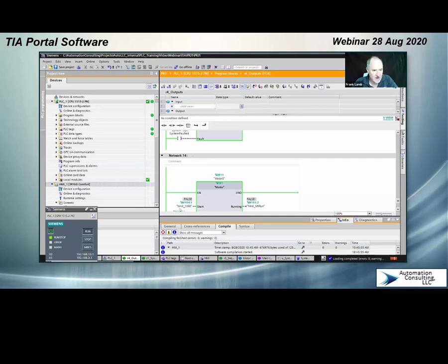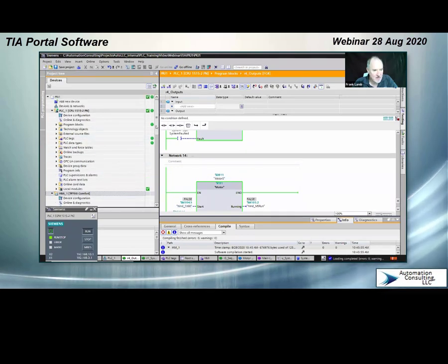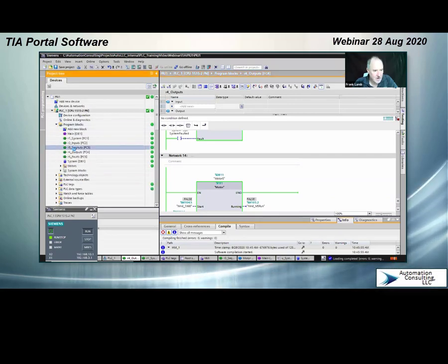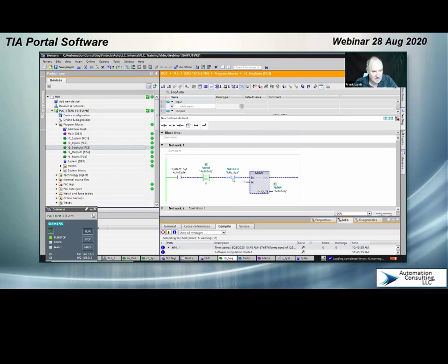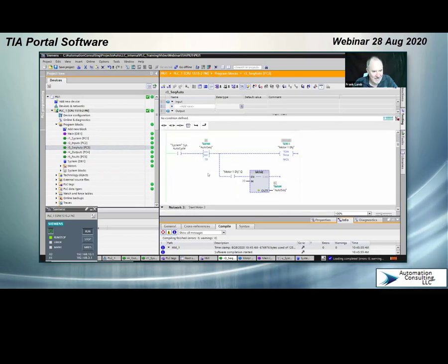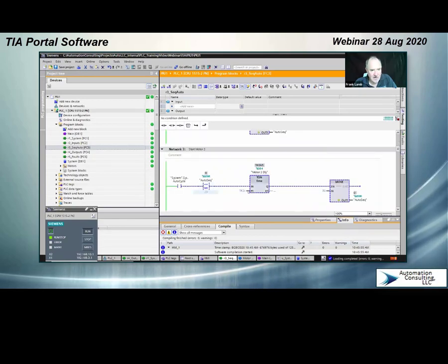So they sequentially start, and the way I did that is I used a very simple sequence. I'm going to go back up to my PLC. Here's my auto sequence. It was already open down here. You see I have a lot of blocks open. This is the way the auto sequence works. If I'm in auto cycle and I press the run push button, I go to step 10. If I'm in step 10, I run a timer, and I used one kind of timer here and a different kind of timer below. This is an on-delay timer. When it's done, it goes to step 20. When I'm in step 20, I use a different timer, and when it's done, I go to step 30.